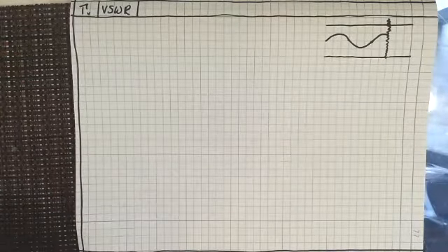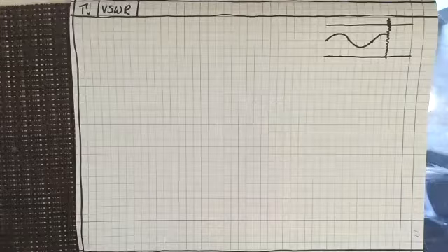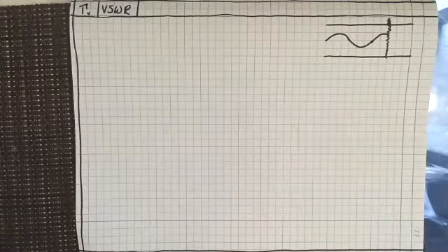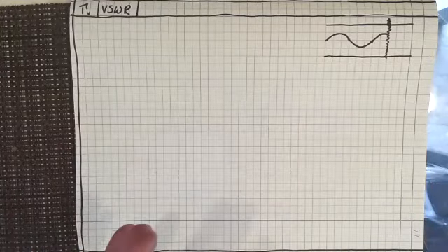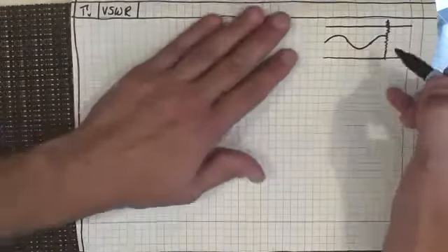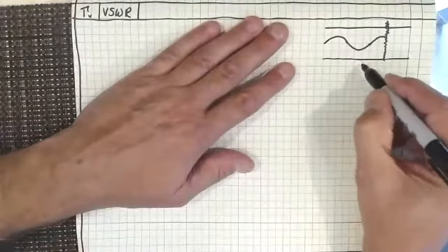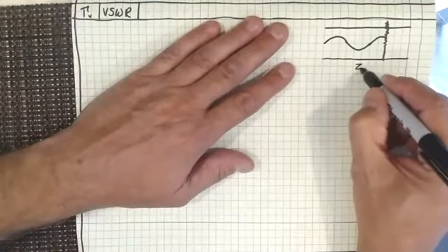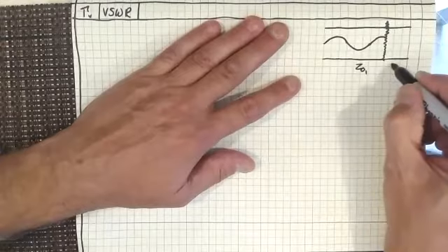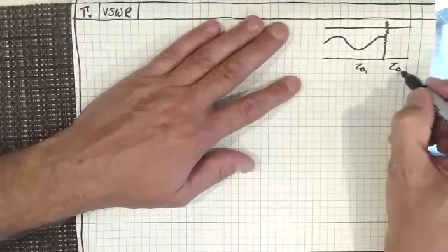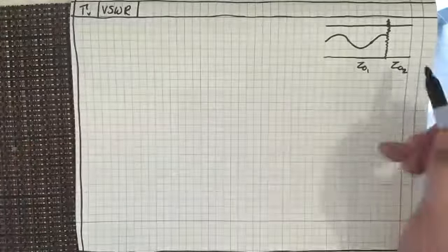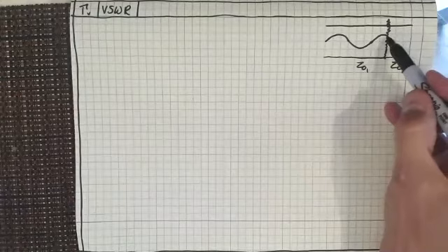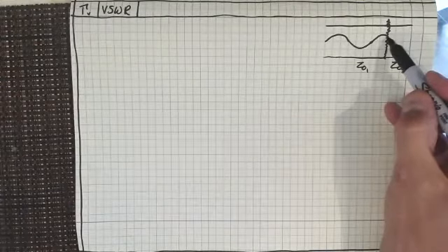Like I'm connecting a 75 ohm to a 50 ohm waveguide, so coaxial cable, if you wanted to think of it that way. And so if this one had Z sub 0,1, and this had a different characteristic impedance, Z sub 0,2, what we would find at the interface is that we would have a reflection coming back.